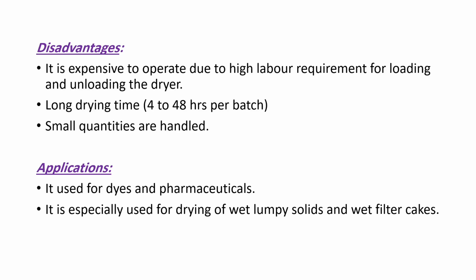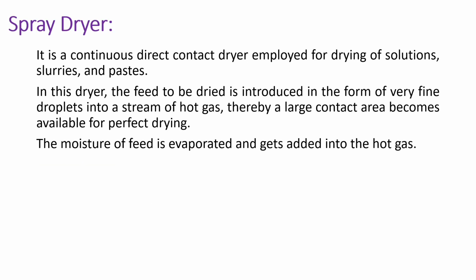Then the spray dryer is a continuous direct contact dryer. Liquid feed is converted into very fine droplets, and these droplets contact hot air, so the moisture evaporates rapidly. Then dry powder is produced, because we will feed slurries or solutions or pastes, so the product will be fine powder.